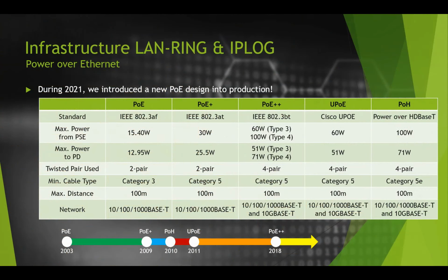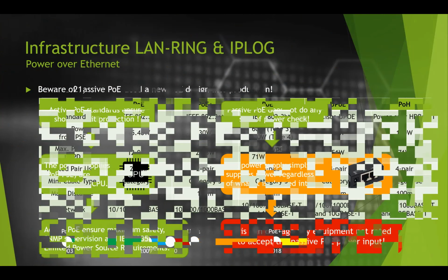Most of our switches support PoE power supply, which can be recognized from the label itself. In the basic version, it is PoE up to 30 watts according to the IEEE 802.3at standard. In addition, the PP versions support PoE up to 95 watts from one port of all active PoE standards.